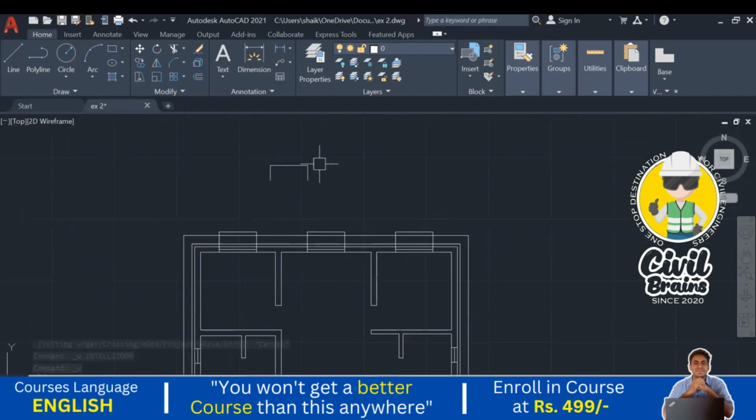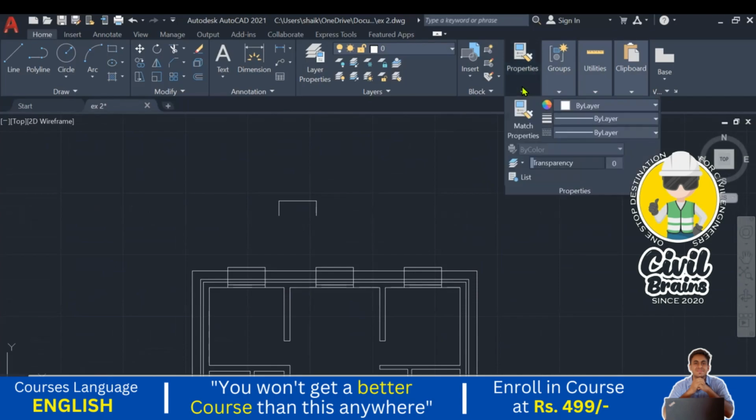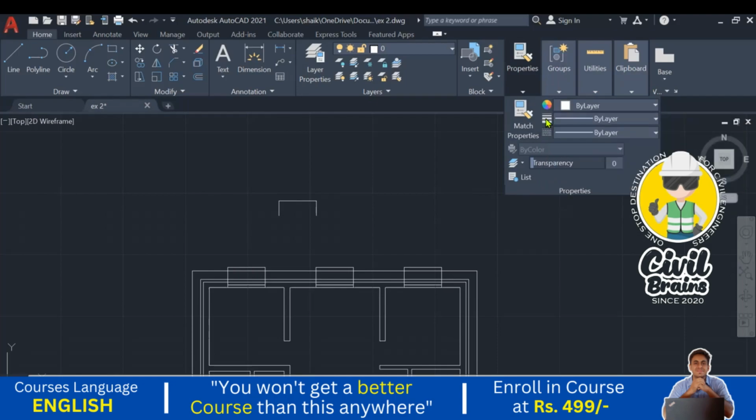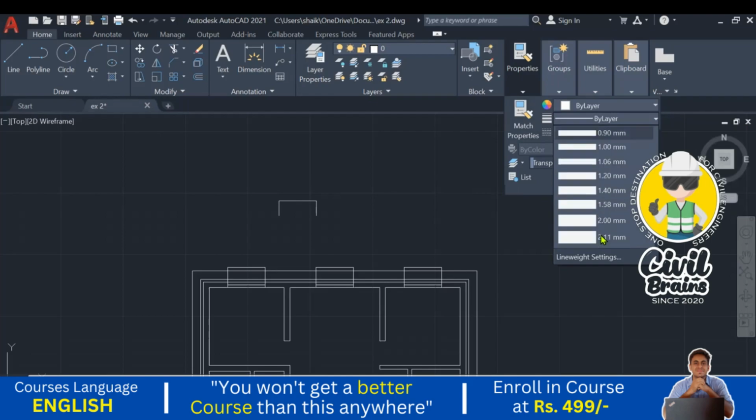So how to show the dotted lines? I will show you. I just go here to draw the dotted lines. All of you just observe here. To draw the dotted line, we go to the property section. Here you can see by layer, and here the line options. So this is the color change. If you want to change the color of any object, you go here. If you want to change the thickness of the object, you go here. Thickness of the line. You can change the thickness of the line.